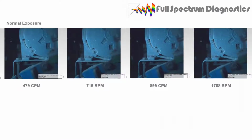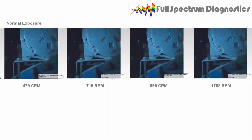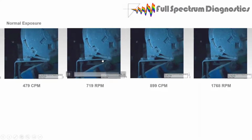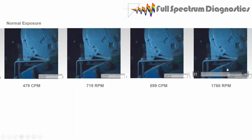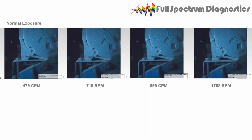Now, I get all that put together, and this is what I want to get to. I want to be able to see faults in this detail that aren't all choppy and blocky. This is a nice, clean animation. It's 4 different frequencies. They all might be natural frequencies, but one of them is 719 RPM, the pump speed, 1768 is the motor speed, and then these are 2 natural frequencies that probably line up with some belt frequencies that are giving us a response. Regardless, they're all highly active operating shapes.